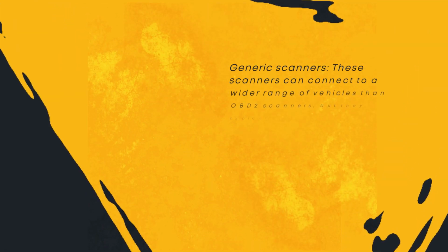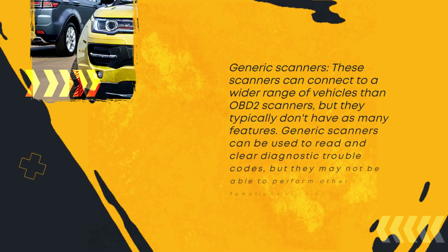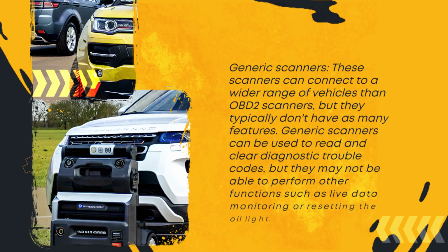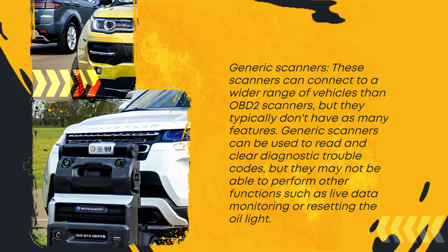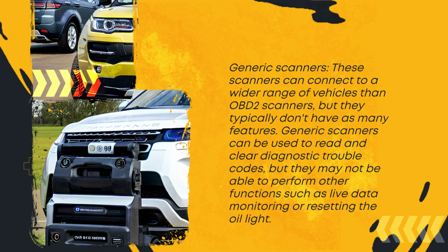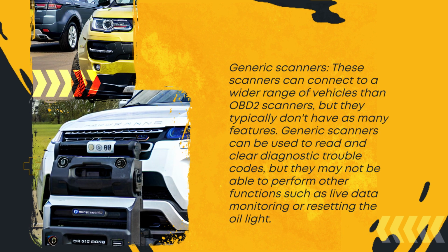Generic scanners. These scanners can connect to a wider range of vehicles than OBD2 scanners, but they typically don't have as many features. Generic scanners can be used to read and clear diagnostic trouble codes, but they may not be able to perform other functions such as live data monitoring or resetting the oil light.